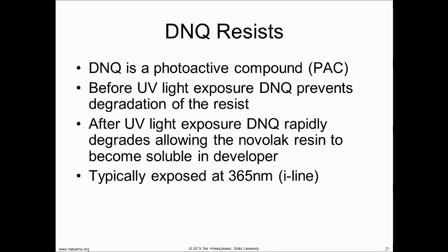And that's so important that we define it specifically as i-line. So the word association here is 365 equals i-line. Does everybody see that? When you go to pick a resist, you'll go to a catalog, and the catalog will have chapters, like i-line. And there'll be the i-line resists, and they're tuned for 365. So does everybody understand that? So i-line is tuned, and that's a type of resist.